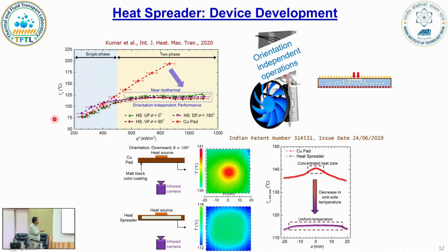You look at the slope of this curve, and that gives you the thermal conductivity, which is 400 watts per meter Kelvin roughly. But as soon as we kick in boiling, look at what happens. Almost no temperature increase, because heat flux can go up to 110 watts per centimeter square, almost horizontal.